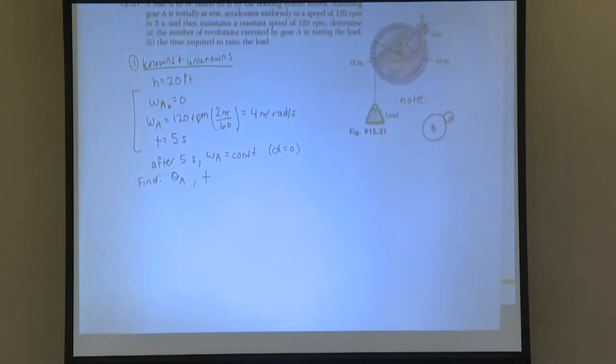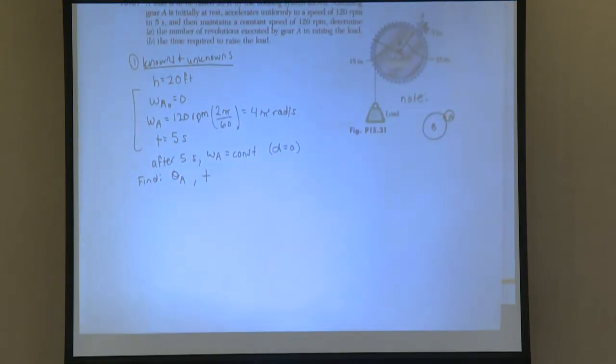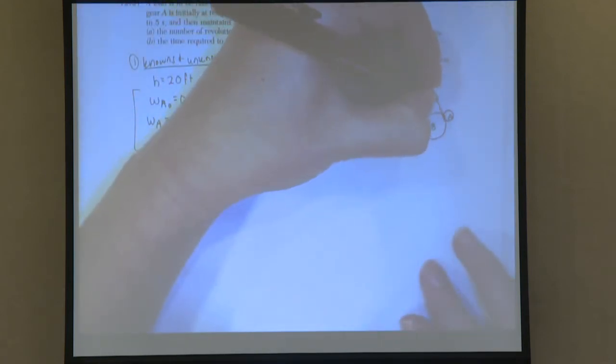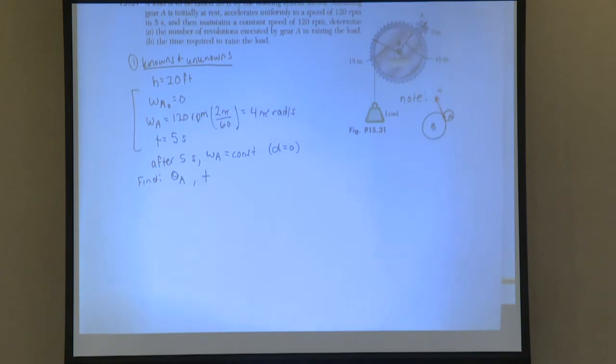We're going to say that these 2 gears, there's no slippage going on. So what does that mean about the velocity at their contact point? Good, so it's going to be the same. I'm just going to assume that that is v. So the velocity at the contact point is the same. And since the velocity at that point is the same, the total distance as they're rotating would also be the same, right?